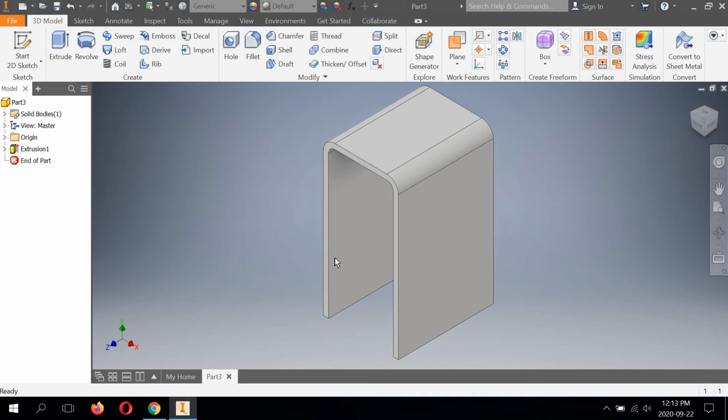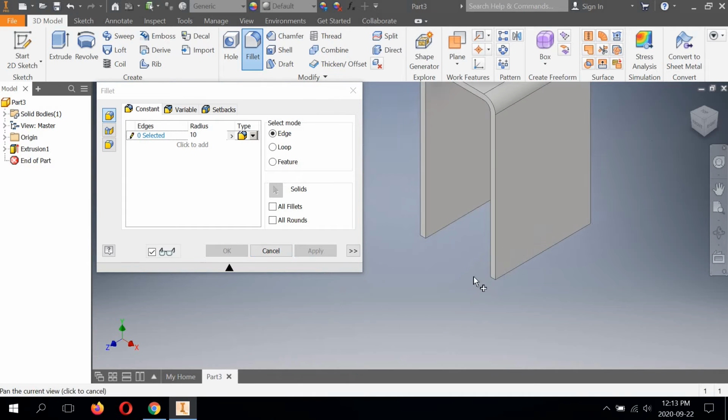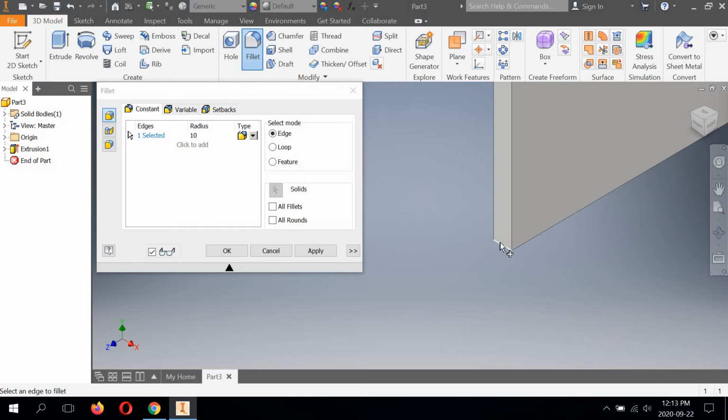And to move forward, we're going to create the fillets here at the bottom edges of the bracket. This is going to help us get started to find where our holes should be positioned so the shaft can be inserted. So we're going to use a fillet feature. We know that the fillet value is 10. We've talked about that. So we type 10, select this edge here and this edge, and then select OK.